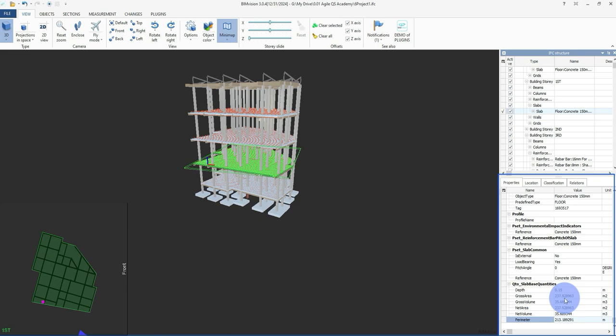So now here you can have the concrete volume, the cubic meter of the concrete, for this floor. You have the formwork to the sides, which is the perimeter, and you have the formwork to the soffits of the slabs, which is 237.9. So see the information that you have now with a single click.